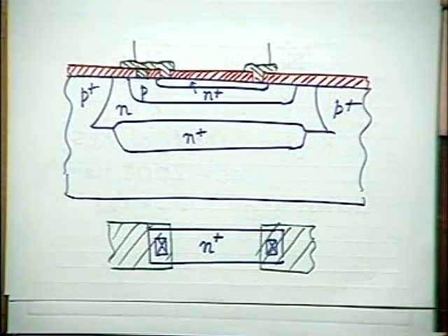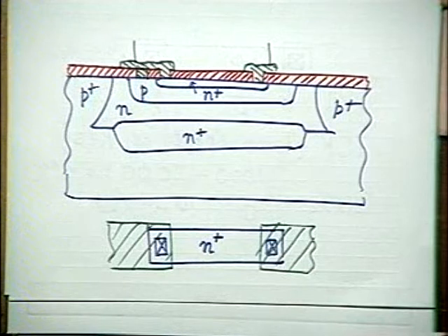So you see that it is possible in bipolar technology to realize resistance of different ranges. Whenever you are interested in realizing resistances of the order of a few tens of ohms or even ohms, you can prefer to use the emitter diffused layer. Resistances of the order of a few kilo ohms or maybe several tens of kilo ohms maximum, you prefer to use base diffusion, the base layer.